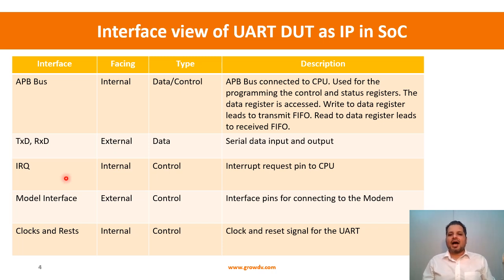And then you have the IRQ, which is an interrupt request pin to the CPU. Again, it's an internal pin because it goes to the CPU. So there will be an interrupt controller in the SoC. It will go to that interrupt controller, and there it will get aggregated and then sent to the interrupt pin of the CPU, but essentially it remains inside. It doesn't come out as a pin outside your chip package.